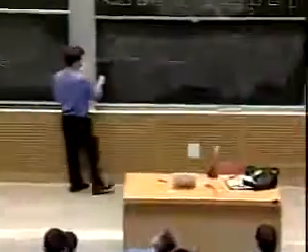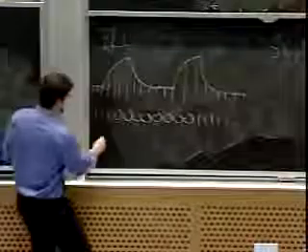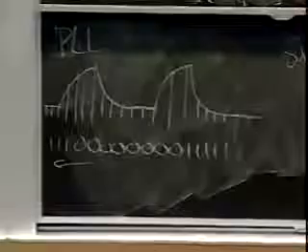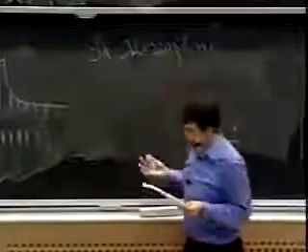So if instead we start decoding this and we see something that's not quite that, suppose we see 3 ones followed by 8 zeros followed by 5 ones. We decode 2 bits worth of information off the wire, and we see that it's shifted in this way. That suggests that I need to shift the signal to the left some amount. This is exactly what the phase lock loop does: it observes the signal as it's coming in, and it computes an amount that we need to shift the signal in one direction or the other. If you wanted to make a schematic for how a phase lock loop works, we have our sender and our receiver.